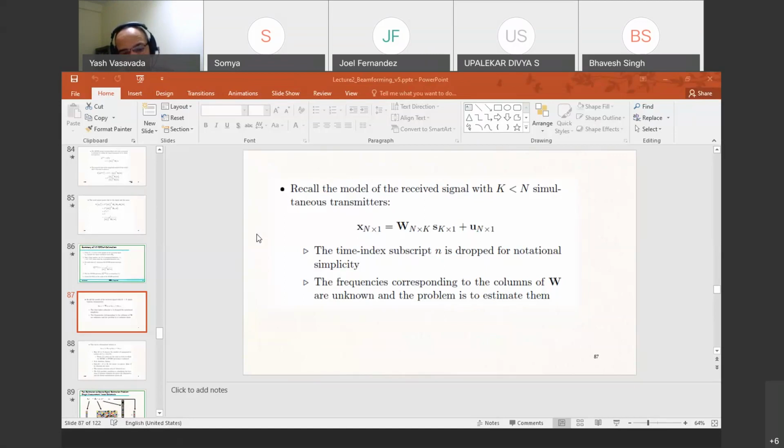Okay, so another advantage of MUSIC compared to the power spectral density technique is that you don't need that hardware. You don't even need a filter, specifically the bank of FIR filters that are required for the power spectral density based estimation. All you need is a numerical equation solver. You just solve for the roots of that equation and this is solved.